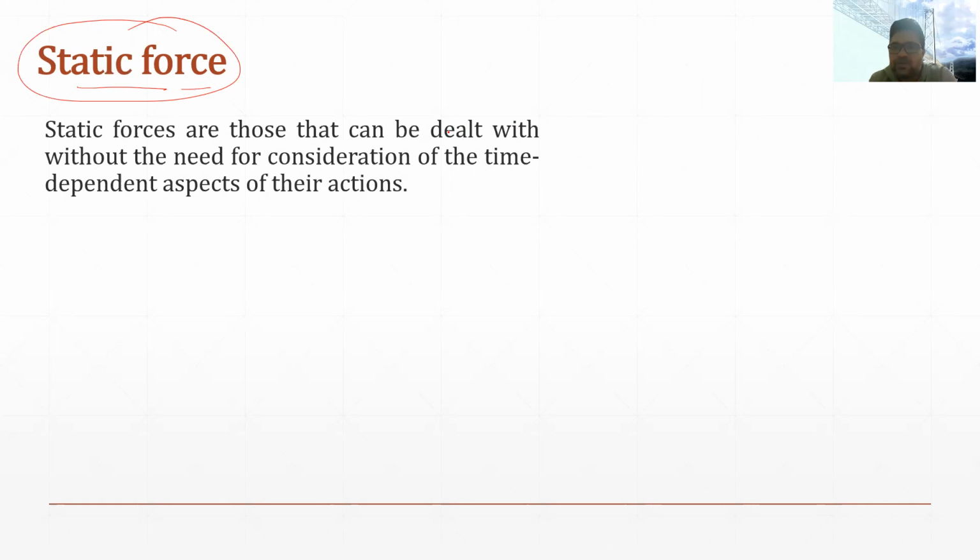Like when we design our building for the dead load and live load and the environmental load like the earthquake load, in that case, we generally consider the dynamic part also. But as we will be dealing with the ordinary building, we will assume that our building is experiencing only the dead load and live load. And for that, the consideration of this static force is enough. So as written here, static forces are those that can be dealt with without the need for consideration of the time dependent aspects.